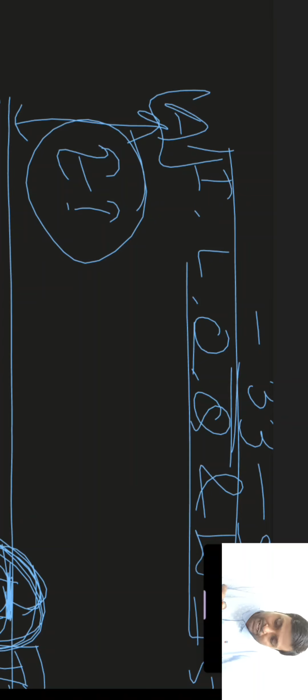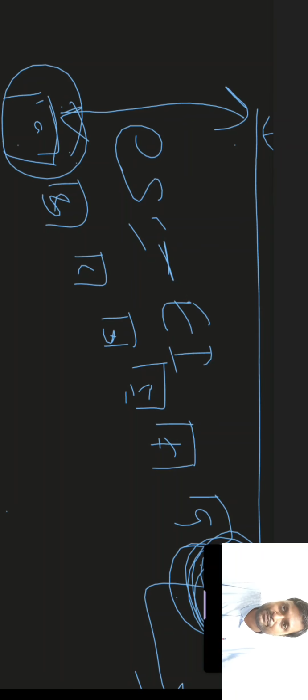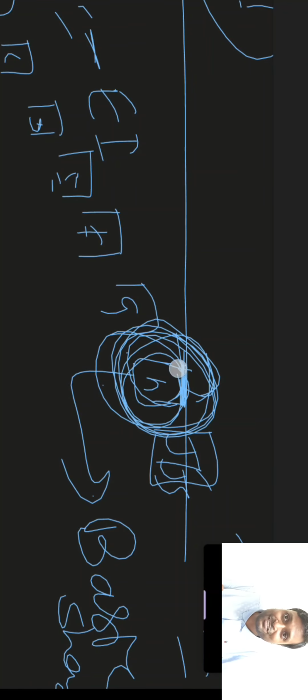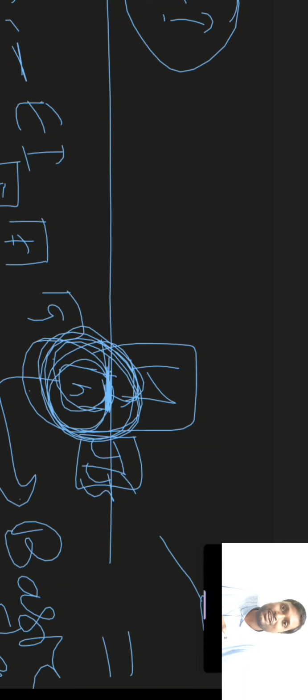That is, for fundamental deviation A, this écart supérieur will be minus the écart inférieur of the hole. This type of relation for the corresponding fundamental deviation exists up to the fundamental deviation of small h, or you can say the fundamental deviation capital H. For hole it's capital H, for shaft it's a small h.